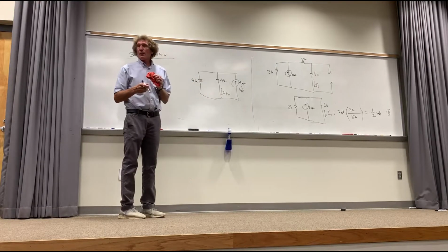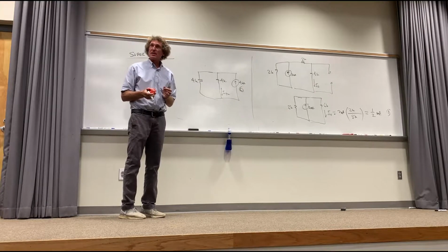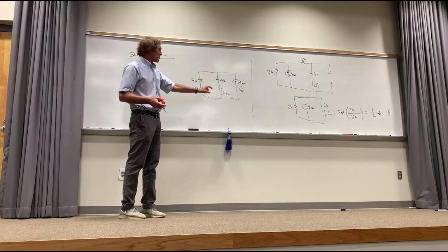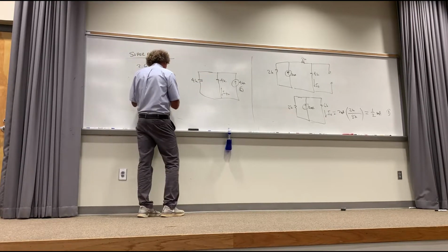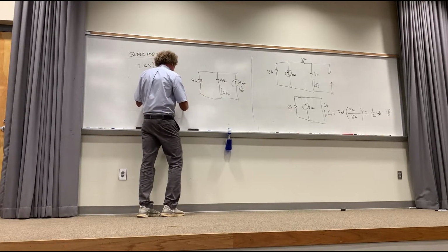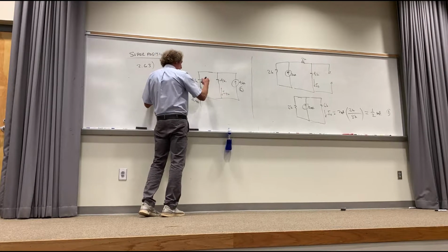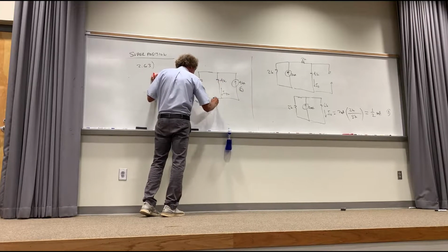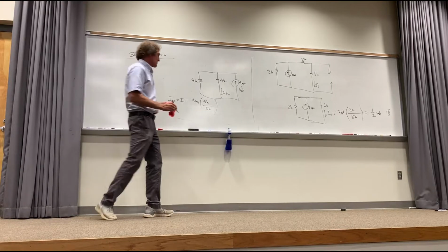Agreed? Well, common sense tells you if they're identical resistors across the same voltage, they better have identical currents, right? How many see that exactly half of that 4 milliamps goes to that 4K? But just for the record, I4K, right there, or I out, would be equal to the net current 4 milliamps times the opposite resistor 4K over the sum of the two, which is 8K, right? And that's exactly 2 milliamps, right? So that's 2 milliamps.